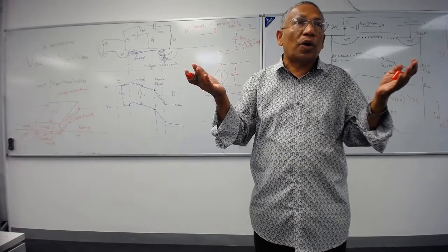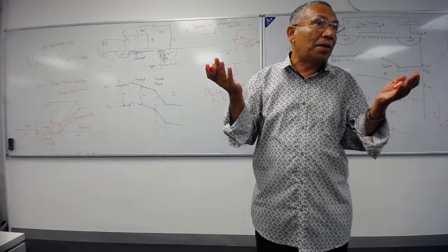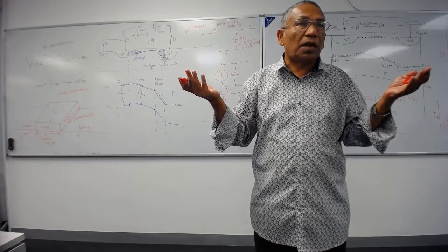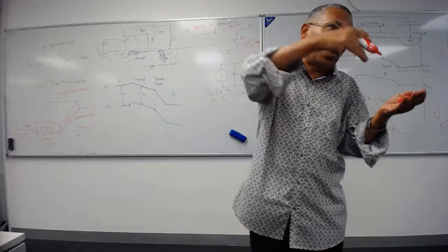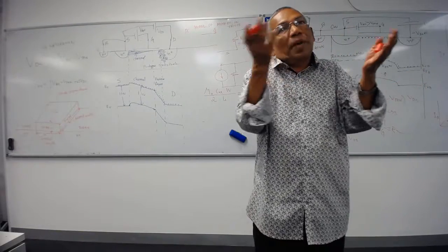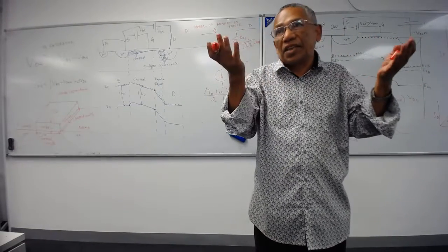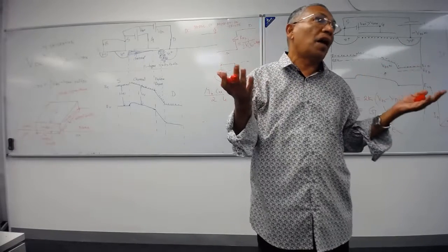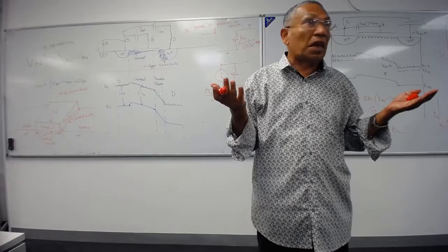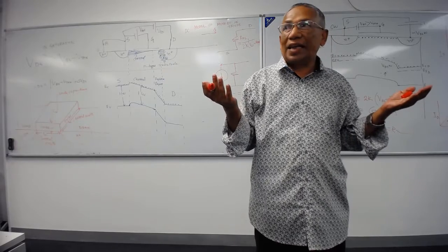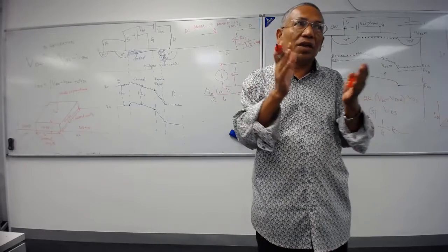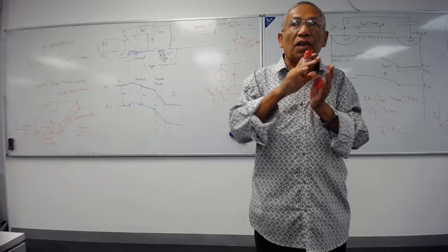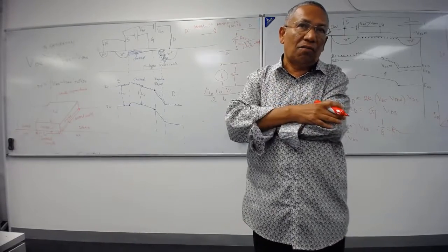You want the corresponding base current, divided by beta set, 10, 15, whatever, so that it is ensured that it will be in that region. And then you find the base current, which will be large, and find the resistance equivalent necessary to drive that current, which will be how much? Sometimes 10, 15 kilo ohm. And if you are getting 900 kilo ohm, that means you are not in the saturation region. You are in the forward active region of the BJT.